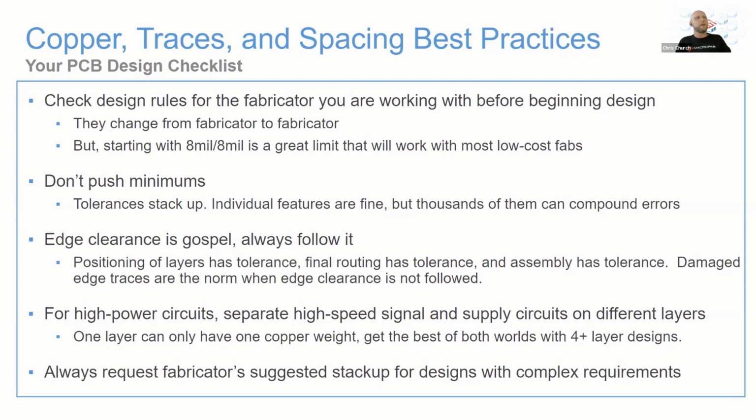Let's consider the edge clearance here. The spacing between copper and the edge of the board is very, very critical. Again, we're talking about tolerances in any manufacturing process. There is tolerance on the board edge routing, and so what can end up happening if you get within that keep out area is that sometimes the bit, as it's wobbling, can actually get too close and start to expose that copper near the edge of the board.